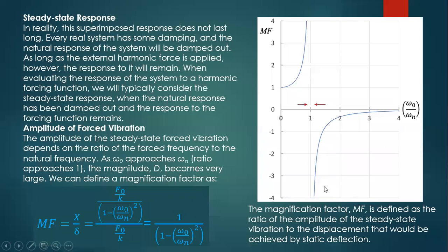Steady state response. In reality, these superimposed responses do not last long. Every real system has some damping, and the natural response of the system will damp out. As long as the external harmonic force is applied, the response to it will remain. When evaluating the response of the system to a harmonic force, we look at the steady state response, when the natural response has been damped out and the response to the forcing function remains.